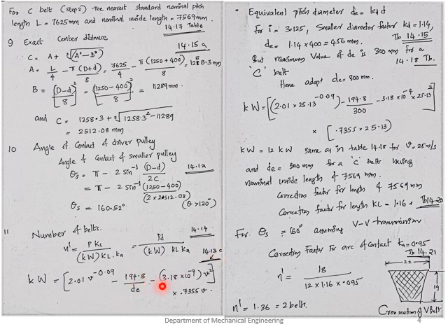You can find the equation from page number 295, and you have to substitute the value for D here. We have the equation for DE, KD into D. If you substitute that value, we obtain the value for I and we have the value for D. When you substitute those values, you will obtain the value for DE as 456 mm. But from table 14.18, the maximum value of DE is 300 mm for a C belt. So we can substitute the value 300. Here we will be adopting the value of DE as 300 mm.